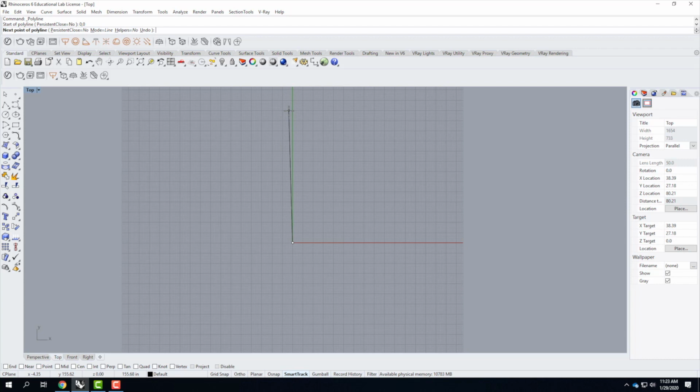And so if I want that, I'm going to type in another coordinate of that next point. And that coordinate in absolute coordinates is 0, 24 apostrophe, or 0, 24 feet. So I'm typing that value in. The apostrophe, the single apostrophe, is for feet. The quotation mark is for inches. So you can get used to doing that.